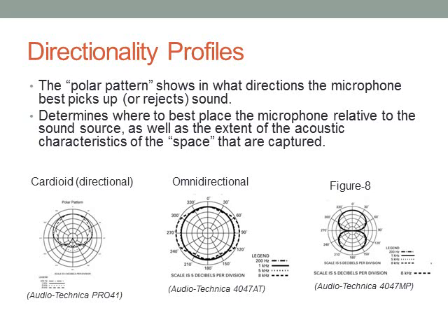This type can also have hyper and super variations, which allow for more sound pickup in the direction opposite the primary direction. The next is omnidirectional. Here, the pickup region is equal in all directions, so the microphone can pick up sounds surrounding it rather than from one direction. This can be used with groups of sound sources or in a studio setting to also capture the sound quality of the space. Next is the figure 8, which provides pickup regions mainly to the front and the back of a microphone, while minimizing sounds from the sides.